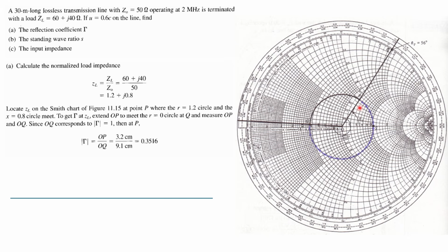While you are solving, please keep your Smith chart and solve this question with the help of your Smith chart. You can pause for some time and then do it along with me. Now, did you get the value of R equal to 1.2? Just locate it. R equal to 1.2, and you can highlight this circle. Okay, the 1.2 circle. Now, what is our target?